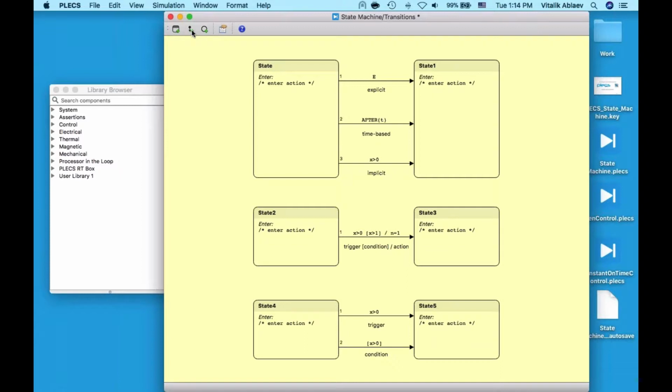The other possible buttons we have up here are a default transition, which basically defines where the simulation should start, from which state. So you get one of these by clicking on this button, then clicking anywhere in the schematic and pointing to the first state that you would like the state machine to start from. And this basically decides the precedence of which state is first.